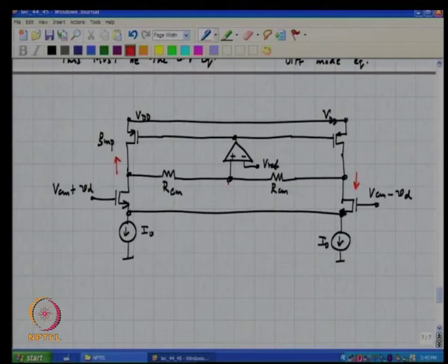So what happens to this potential? This node potential is grounded, this node potential, the source coupled node, is also grounded. If this voltage is 0 incrementally, what is this voltage incrementally? That must also be 0, because that is simply a multiple of the input voltage.